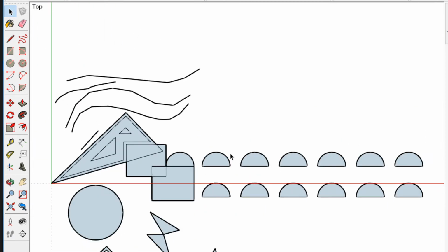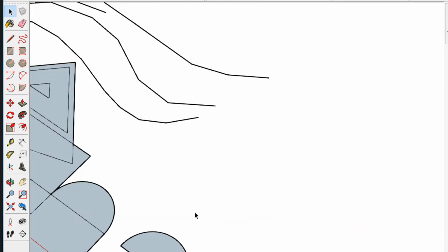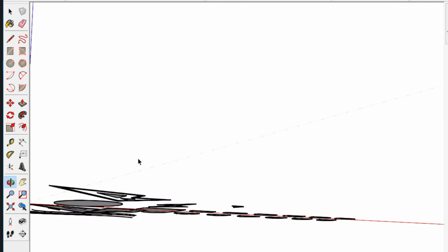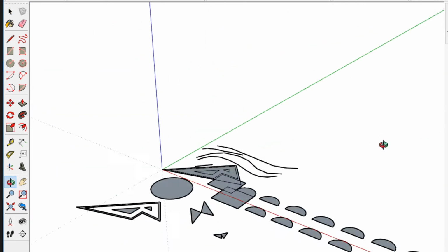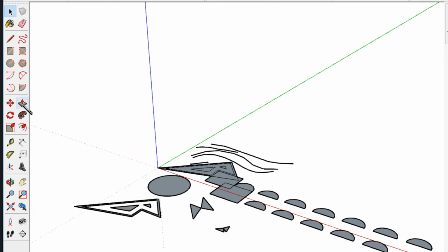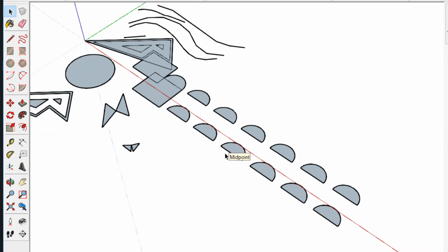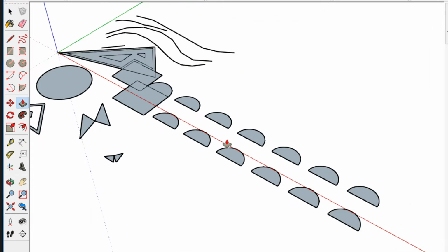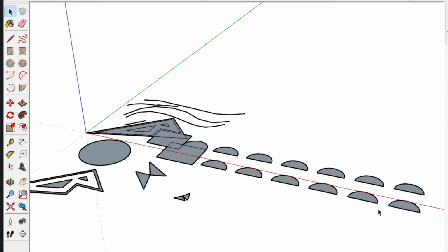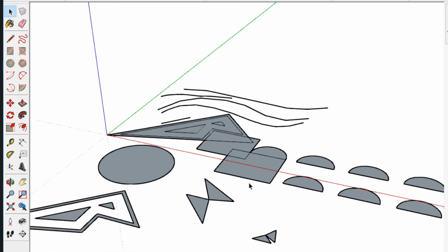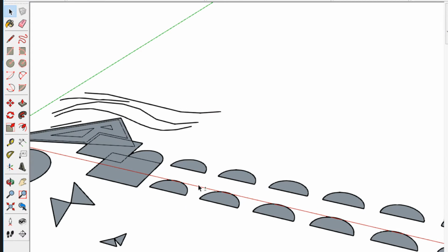So how do you make columns? We need to know the 3D tool. The 3D tool, using your navigation with your camera, is just Push/Pull, this one, or letter P. I personally use, what do I use? Letter S to push pull, because I use it so often, it has to be very accessible. But for now, use P.